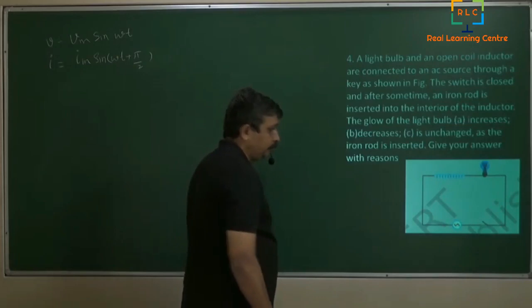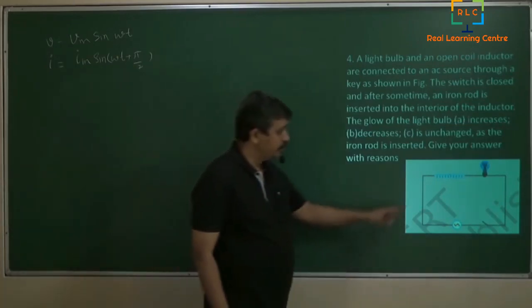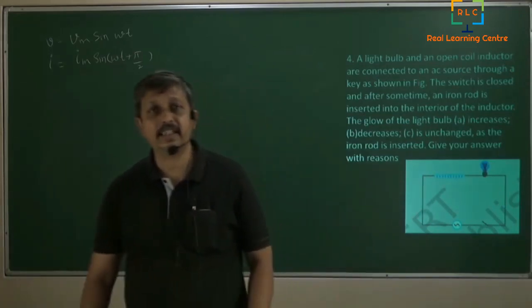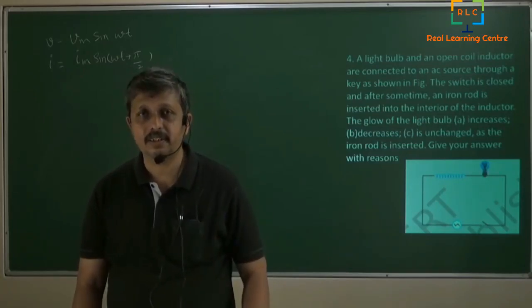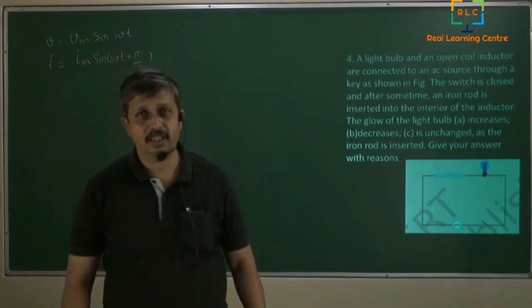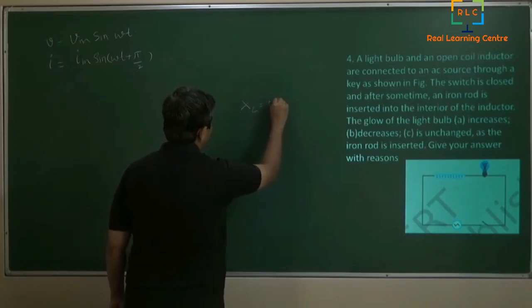Whenever you insert an iron rod in the inductor, you are actually increasing its inductance. If you are increasing its inductance, the inductive reactance is also increasing.